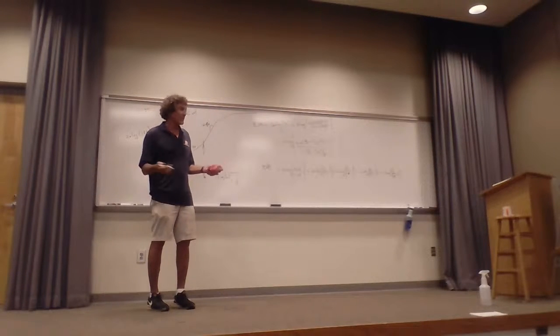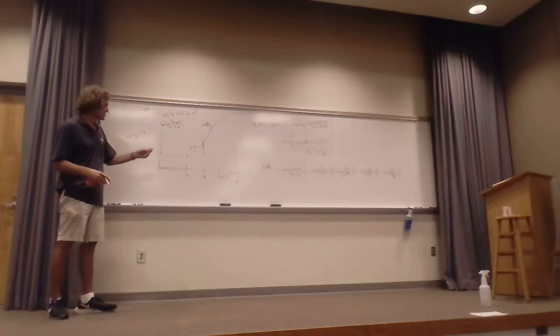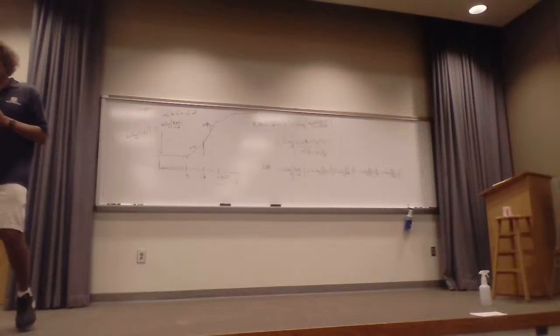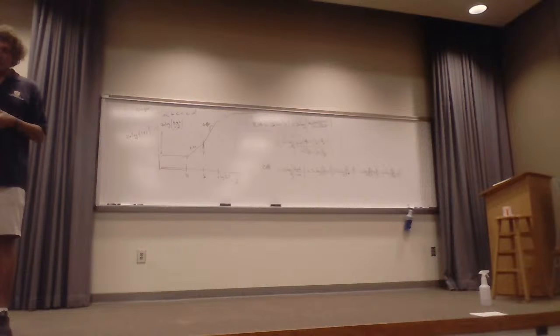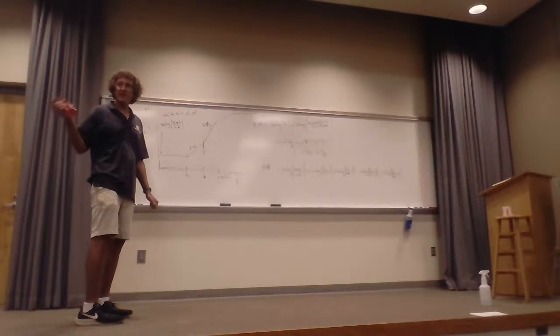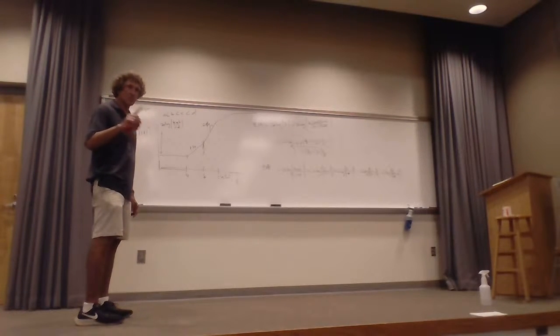And you can extrapolate. If you have a plot of something, you can extrapolate the values for the break frequencies or element values. The very first problem that I think I gave you that didn't have the entire solution showed you something where they used P instead of S. Many, many times in the real world, they'll pick an arbitrary symbol, maybe a Greek letter, could be gamma or whatever, to be designated as the variable S. And it doesn't matter what it is. And then they want an approximate function. Just remember, all these things have to have either F or omega in them to do a Bode plot that's got any meaning.